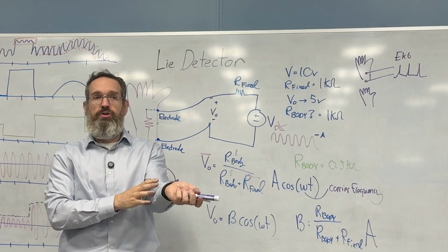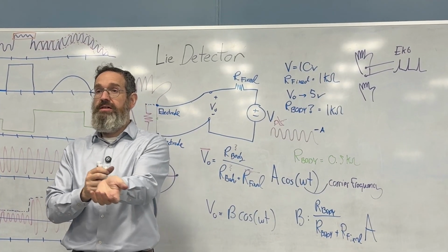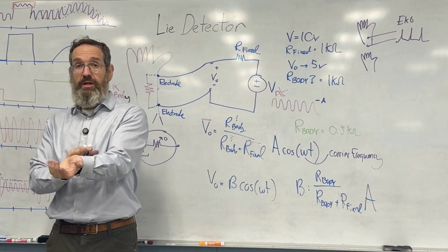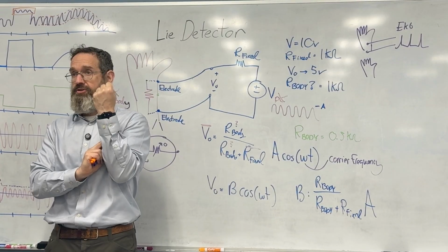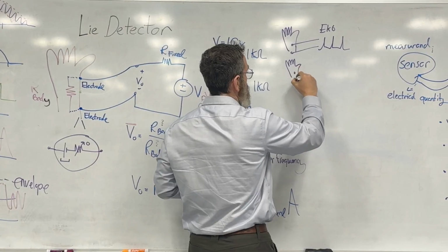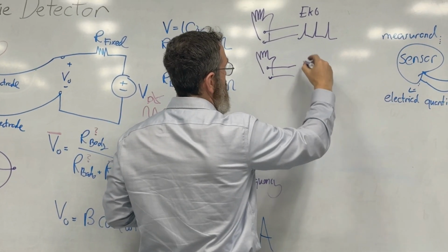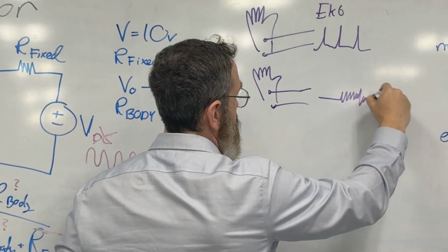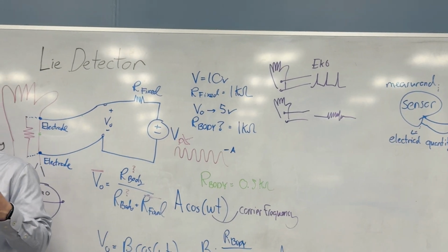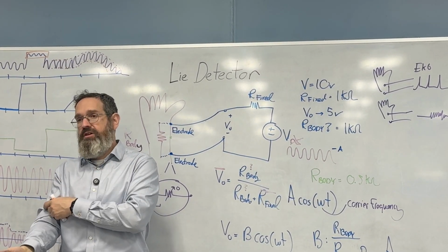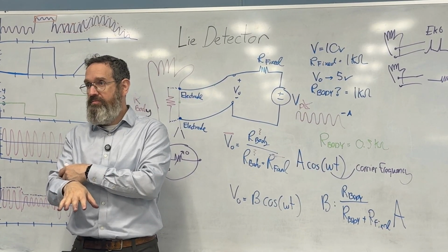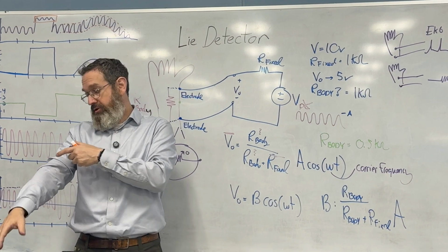Let's say you wanted to measure her EMG. EMG is the electromyogram, right? It is the electrical activity we discussed that is generated by muscle contraction. How would you do that? You would put 2 electrodes on her arm, and then when she contracted her arm, you would see something, right? In fact, the EKG device that you're making, you can just use that for an EMG. Any modifications? No. It's the same device, because you're just putting 2 wires here.